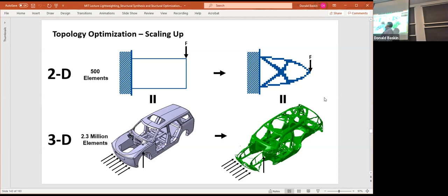This is the only place you can have structure. These are where the elements that would have the maximum density live after you've optimized for density for each of those 500 elements. So your 500-D design space is this one, okay? This is a packaging volume for a car. I'll show you how we get there. This is the result. This is where the optimizer would place density in order to minimize the aggregate strain energy. This is also the place where you get the highest stiffness per weight, the most efficient load path resulting in the most efficient structure, subject to different boundary conditions.